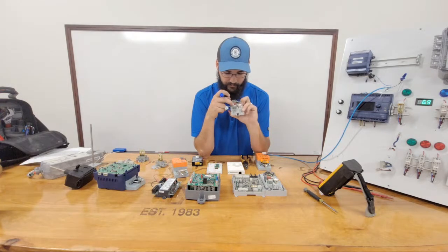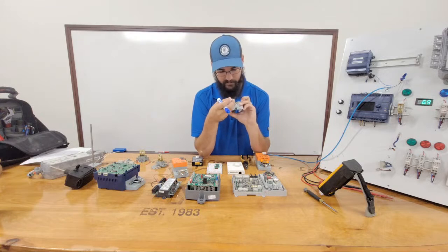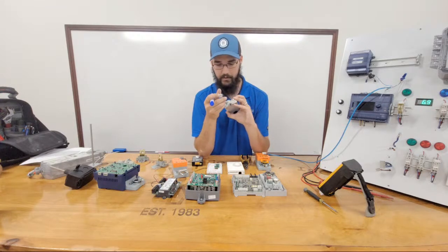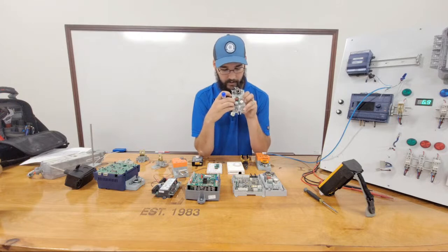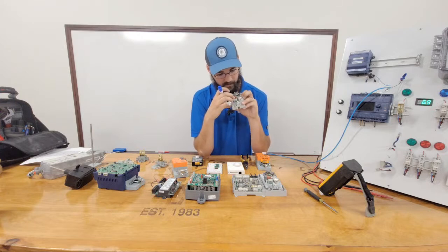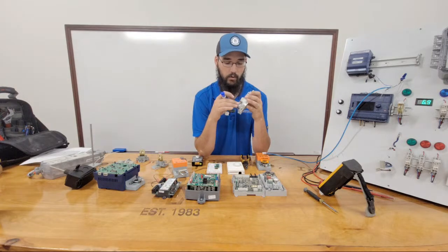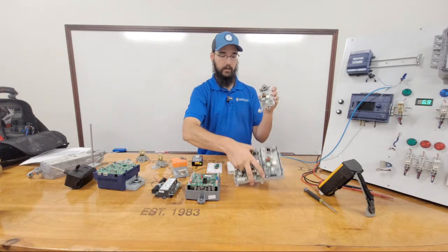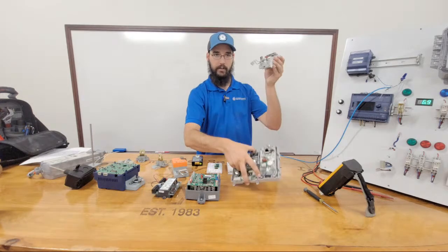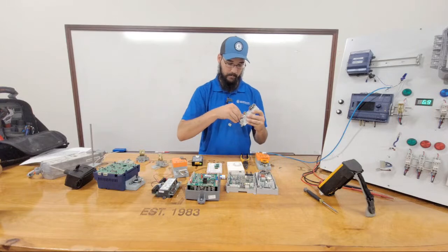In contrast, this Honeywell, let's see, they have a similar setup. So terminal 1 right here is your common, terminal 2 is your clockwise, and terminal 3 they have registered as your counterclockwise according to this one. So this is the same actuator, I just have one taken apart.